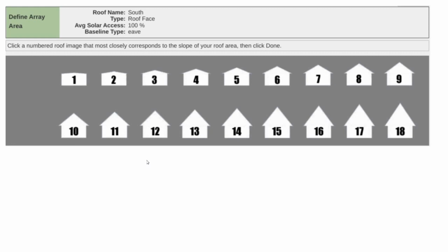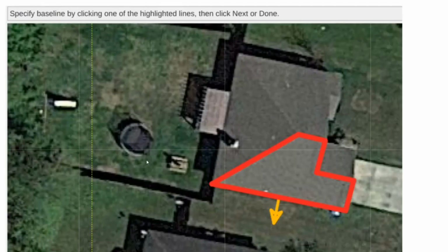So how accurate do these roof areas need to be? It depends. Many jurisdictions require a 3 foot offset from the roof ridges and rakes, which are the sides and the tops of the roof. For structural and accessibility reasons, it is even better to stay 4 feet off the sides and off the top of the roof.